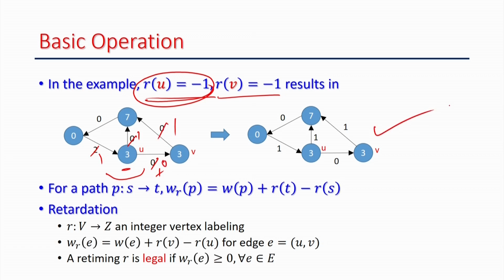So this is the retimed circuit. If I know the values of R u and R v, I can find out that I moved one register from here to this place and this place. If the other nodes are 0, then I know that after retiming the circuit is like this. There are two registers initially here; I move one of the registers to these two places, and I keep one register at the original place. This is what retiming does, and you can see here the maximum delay will now become 6, right.